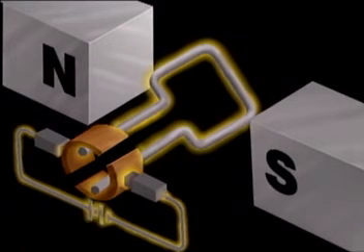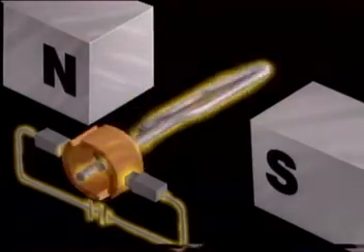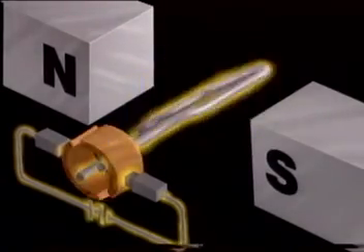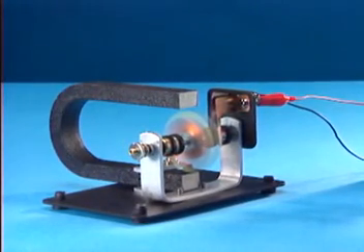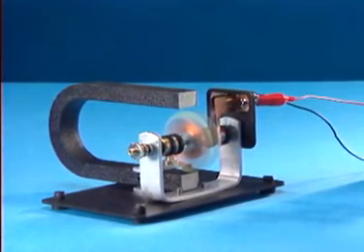Once there, the brushes reestablish contact with the commutator, supplying current and thus ensuring the continuous spin of the armature. This ongoing process, current to the armature, interaction of opposing flux lines, and magnetic push on the armature, is what creates movement in an electric motor. Any work that a motor performs is the direct result of this process.